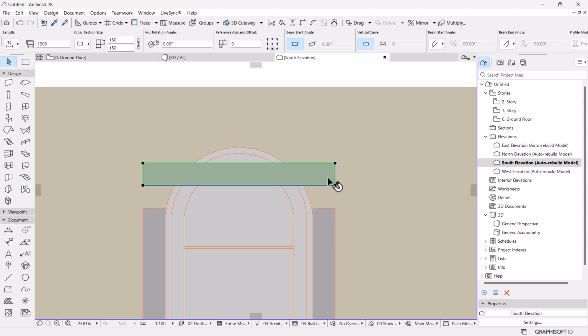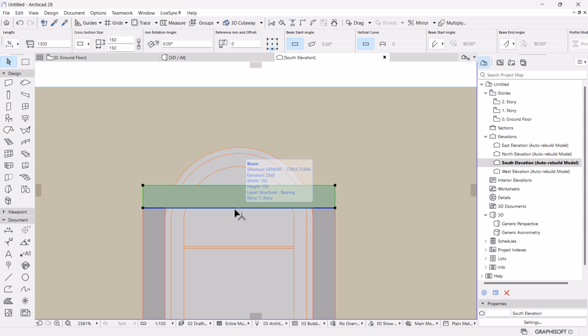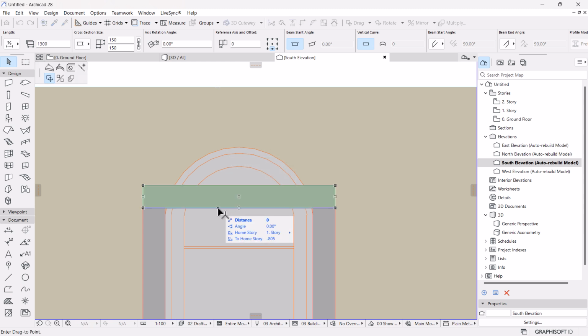Yes. Then you can drag it down again there. So from here, you can either go to its settings and convert this into an arc, or just click on the reference line like this and curve vertically like so.